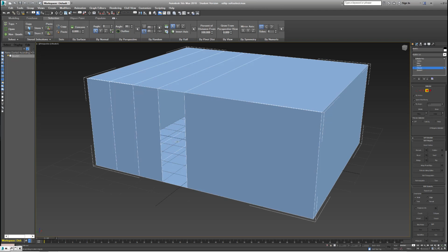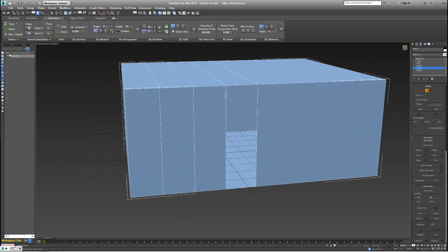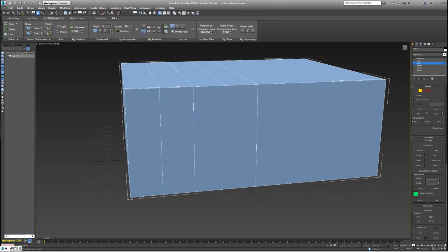It's also kind of good practice to have a bit of a bounding, you know, between this top edge, between switching axes. You want a little bit of some sort of a plane here, however small, because it's going to help it generate a more solid geometry. So I'm just going to hit Control Z for that. Hit Q to get out of that, and I'm going to select my edge. We really just want to create a horizontal line.